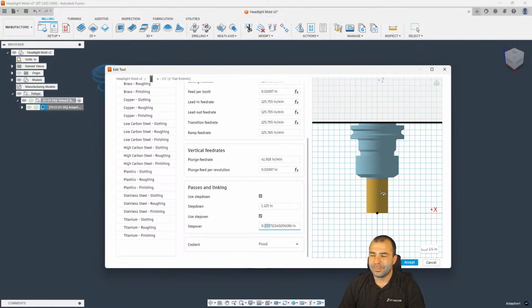Now, the volume of material removal may or may not be more or less. However, what you're going to find out is when doing adaptive clearing, you never really use the full width of the cutter, of course. You're always going to keep it under 50%, but you're going to need a lot more torque, right? So if some of you are old manual machinists that worked on a Bridgeport like yours truly did, there's a reason why we conventionally mill versus climb milling, right? Actually, we climb mill now versus conventional milling because of the amount of torque it takes for that tool to get a bite in deep material going to the thinning side of it.